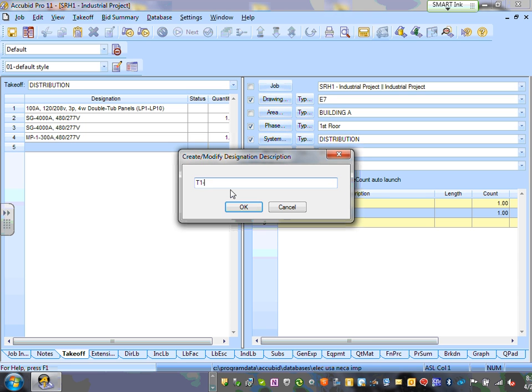And that's where we start digging into. Okay, let's just say it's 75, guys. 75 kVA for your receptacle panel. 75 kVA. If you look at your lighting load, guys, for the time being, you can adjust it. 75 kVA, and the voltage is 480. And again, you can fill this 480 dash 208 slash 120. That's my transformer. Maybe double dash. Here's how we do it. Voltage. So that's my transformer. 480, 208, 120, 75. Okay, it.